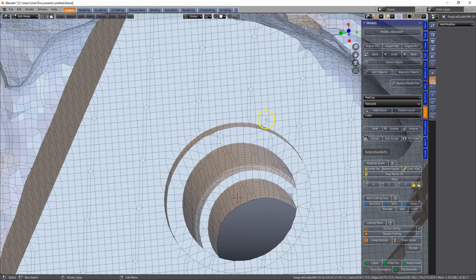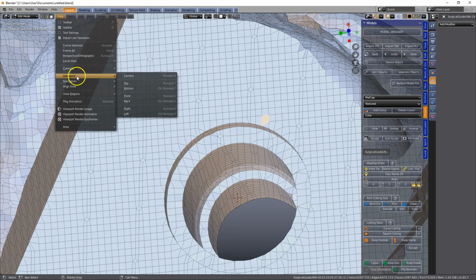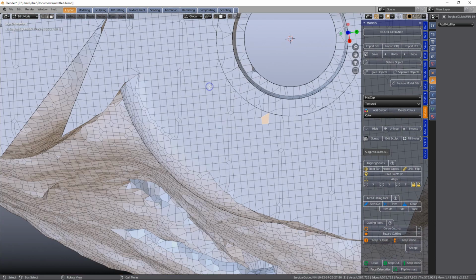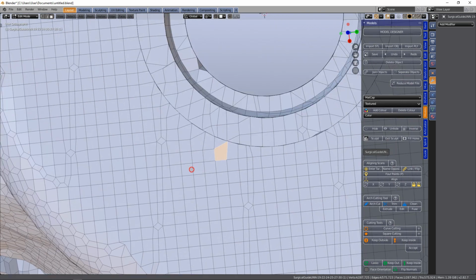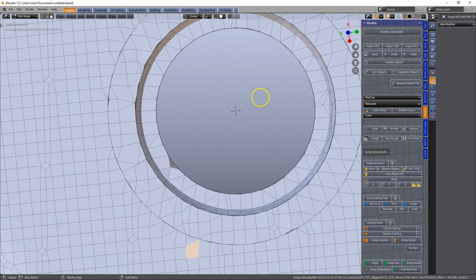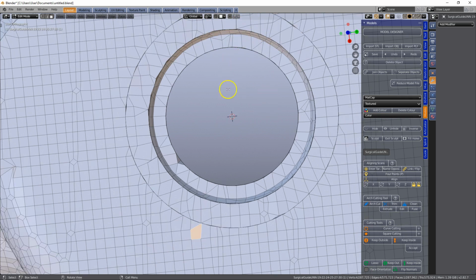The next thing I'm going to do is go to face selection mode, click on a random face, and then go to view, align view with the top. This now places the face parallel to my computer screen. We know the cursor has been placed in the center, and that we're looking right down the center of the hole. I can also see that the hole has not been designed correctly because it is a slight taper. You can see the inside circle is a bit smaller.